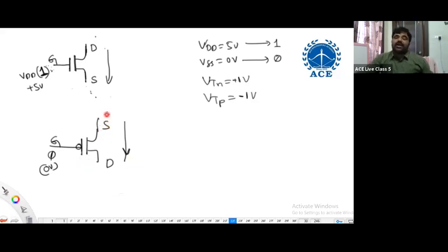Check it correctly. When you are connecting, source is at higher potential than drain, because when you are applying that positive potential, it must be sourcing holes, because a P-channel MOSFET expects holes to be injected into the channel. There I need to connect a positive potential. Sourcing the carriers is the source terminal. For a P-channel MOSFET, sourcing is a positive potential because it has to repel the holes into the channel. The channel is getting P-type carriers, which are holes. And here it must be right, sourcing.